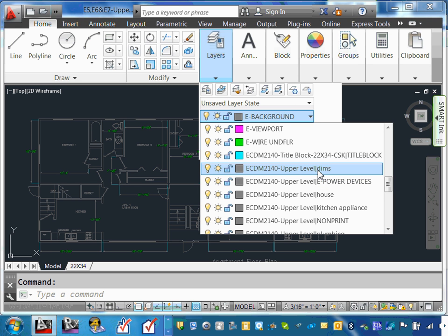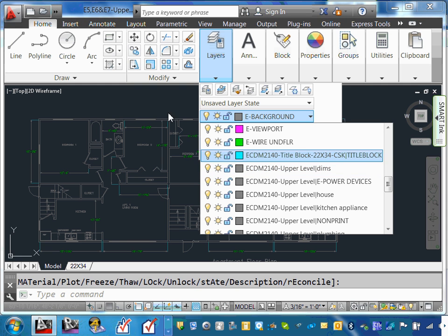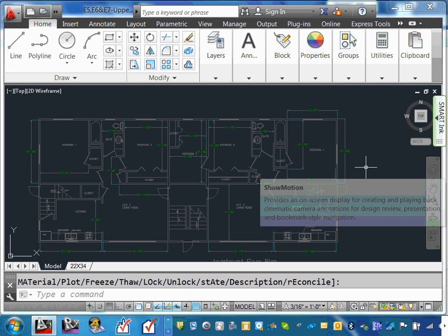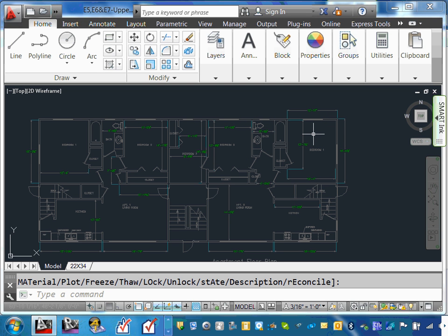If it's bothering you later on, you go there and turn it off. Can you see how it turns off? I would rather you keep it right now, because when you lay out your receptacle, it's nice to have the dimension. It helps you. Remember when we were saying the 6/12 rule? It helps you with the 6. So turn it on right now, but you can turn it off at the end. Now here's your dimension. Cool. Everybody got that one?